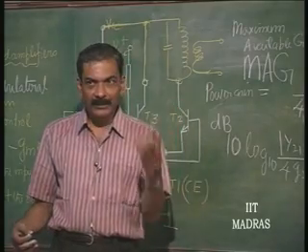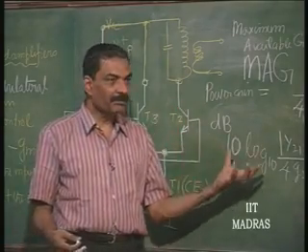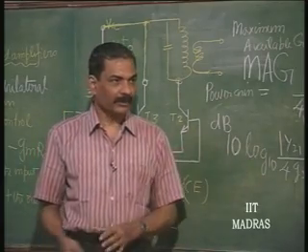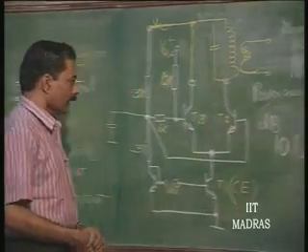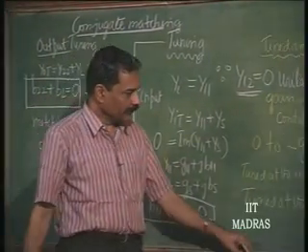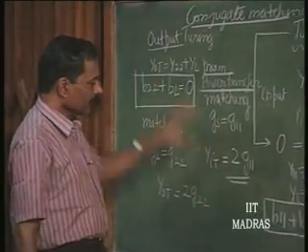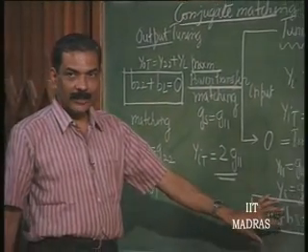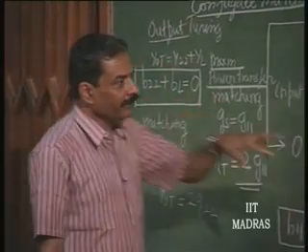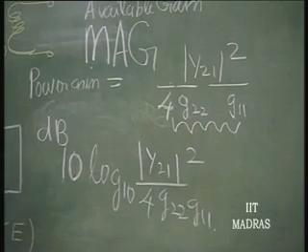And the sensitivity of the receiver is always determined primarily by the IF strip, how good your IF strip is. Okay. So, this part of the design is going to involve only these things: tuning at the input, tuning at the output, and evaluating the maximum available gain. Okay.